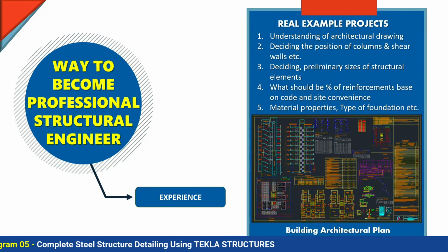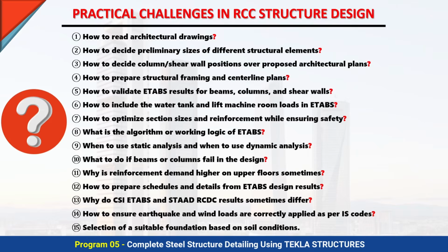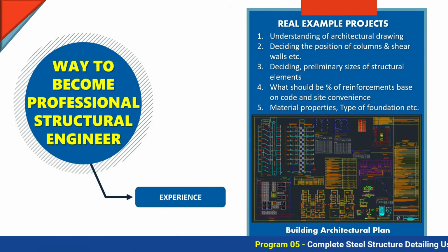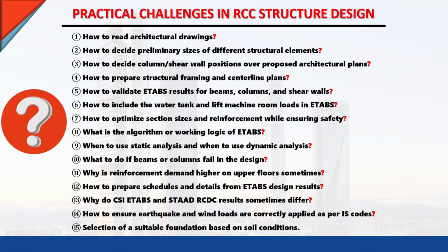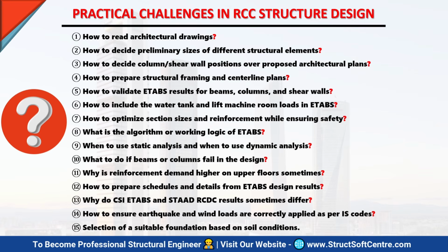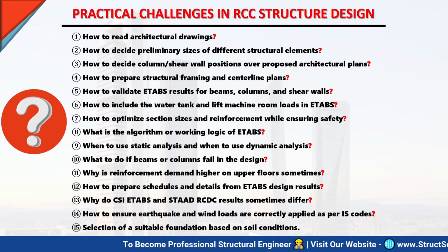So whenever you are going to deal with real projects, you need to know how to read the architectural drawing, how to decide the preliminary section sizes of the elements, how to decide the positioning, the orientation, the material properties, how to do the modeling, how to find any problem in the modeling, how to do the load calculation for static, for dynamic, for the lift machine room, for the overhead water tank, how to do the calculation for temperature loading.